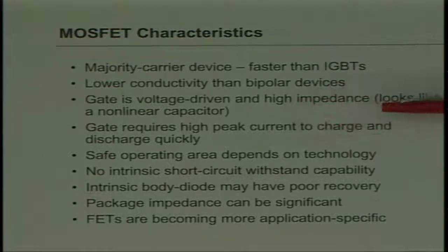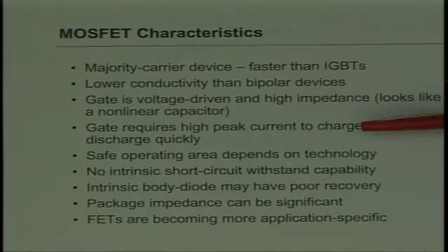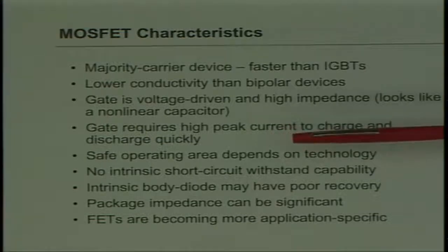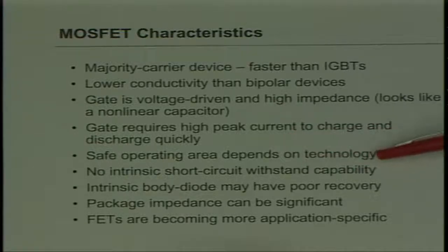They're gate-driven with a high impedance gate that looks like a nonlinear capacitor. It's very similar to IGBT. The gate drive, even though it's a capacitor, you still need a relatively high peak current to be able to charge and discharge the gate capacitance quickly and make it switch. The safe operating area is quite variable depending on the device technology.